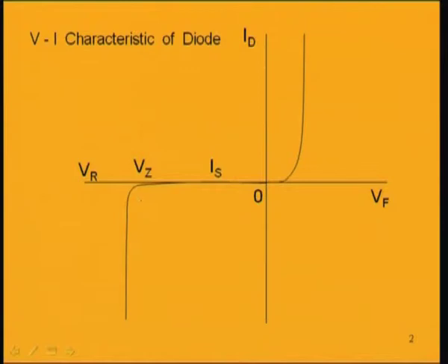But this avalanche breakdown phenomenon generally happens for lightly doped PN diodes. Now, if we increase the doping concentration in P and N type, then we can get the breakdown occurring at an even lower potential. If the doping is high, then we could get the breakdown occurring as low as -5 volt. That phenomenon for heavily doped diode is known as Zener breakdown. Now, there is a fundamental difference between avalanche and Zener breakdown.